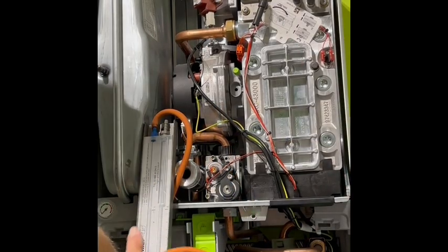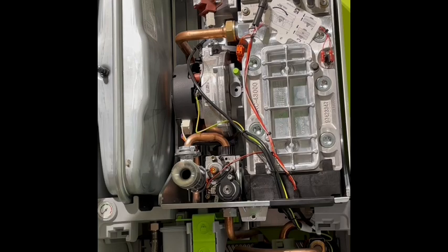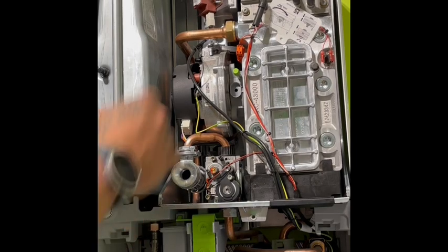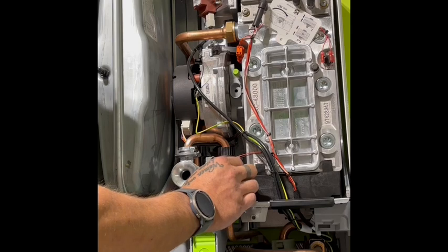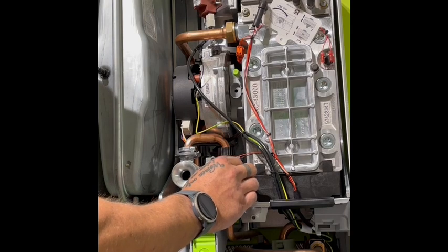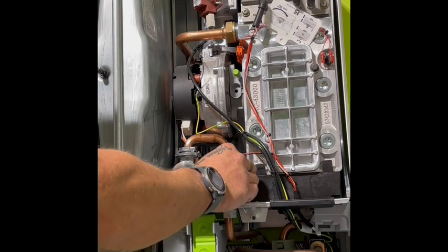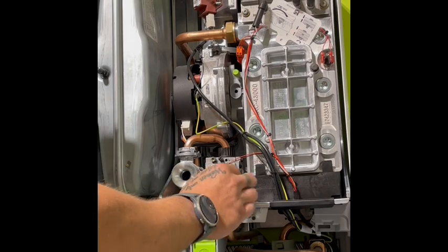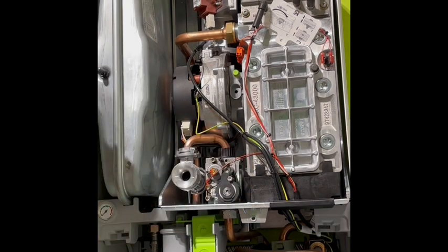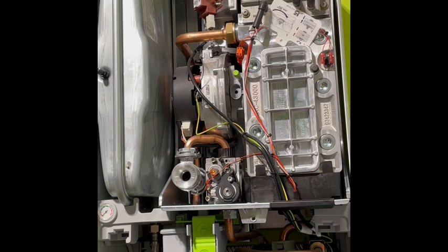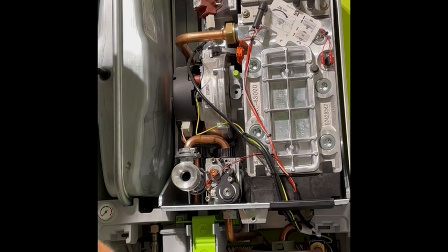Okay, so we've kind of covered the gas valve. It's important to remember that that solenoid can be slow opening. You could have an issue mechanically with the gas valve, so it opens, but it's just not opening fast enough. Just remember that. You're normally looking for a drop of a few millibars on a gas valve when it's opening. So, next in the process is spark.